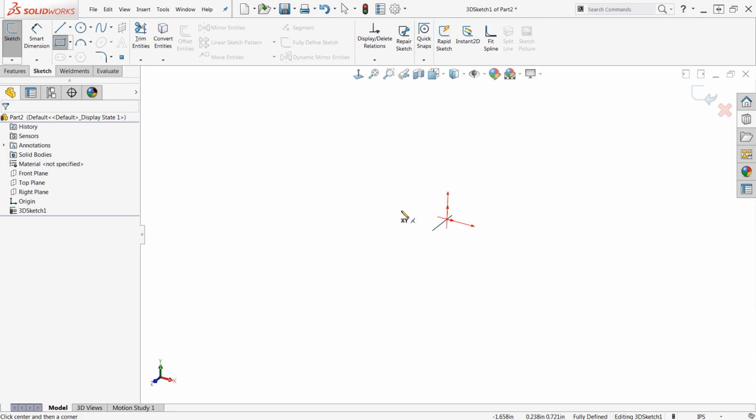While you're in a 3D sketch environment, the other thing that you want to focus on or remember is manipulating the environment so that you're sketching in the correct area that you intend. This is accomplished by pressing the Tab key once you're in a command. Notice what happens as I press the Tab key, it cycles through those standard planes, right? ZX, XY, YZ, ZX. That's what I want, all right? So I use that as I'm sketching and making sure that I'm deliberately doing that.